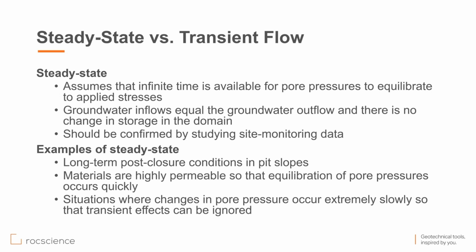Examples of this could be long-term post-closure condition in pit slopes, cases where you have highly permeable material where equilibrium of pore water pressure occurs really quickly, or situations where changes in pore pressure are extremely slow so that yes, you can assume that there is no transient effect.